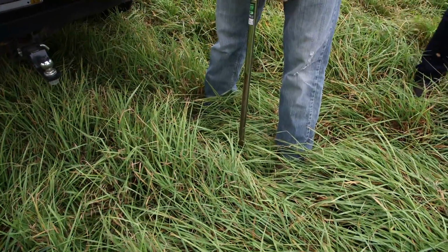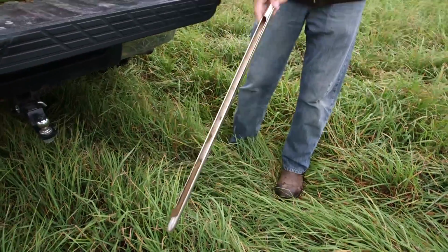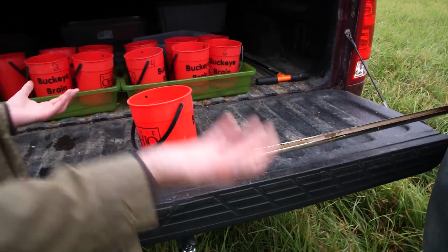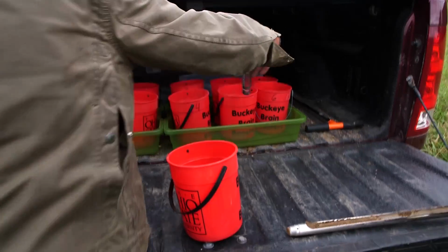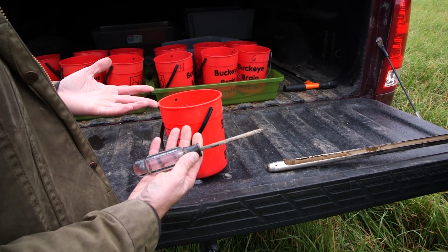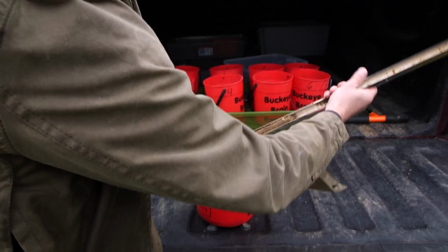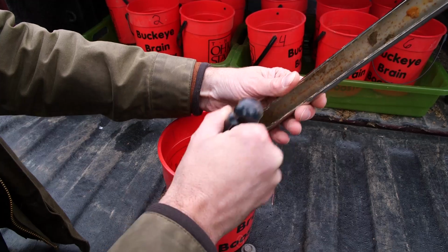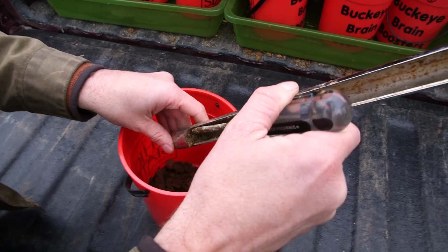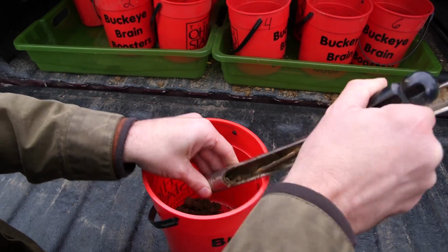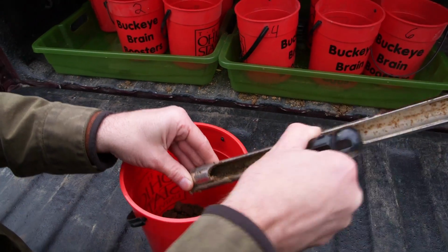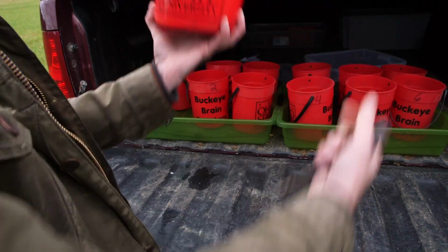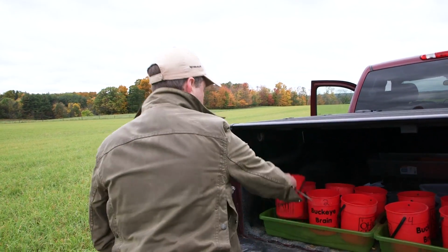All right, and then just twist it a little bit as you come up, and you should have, that is a very nice sample there. So our goal here is we're going to be adding it to our composite bucket where we have other samples from the same spot, and usually it's a bit easier to remove the core with our screwdriver here. So why don't we just stick this right in there, and I will just pop out that core. Usually, it comes out pretty nice, and then down at the bottom it sometimes can get a little bit challenging because we've got some moist soil here. So that's why our screwdriver comes in handy to knock that out. And that is the final product there. So this is bucket 1 from grid cell 1. On to number 2.